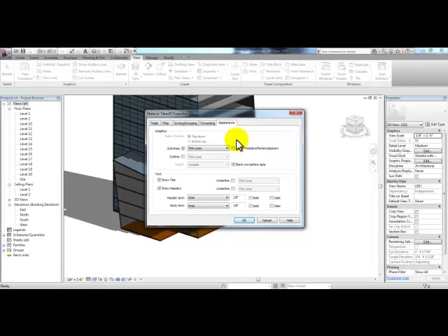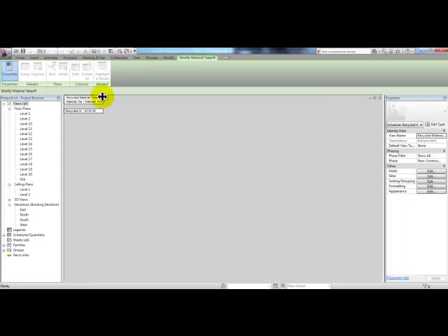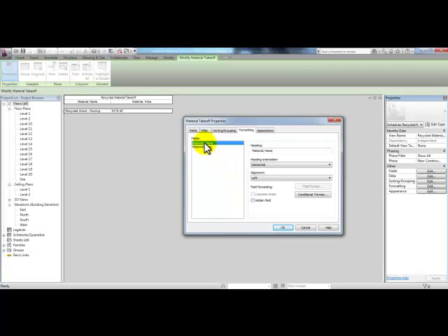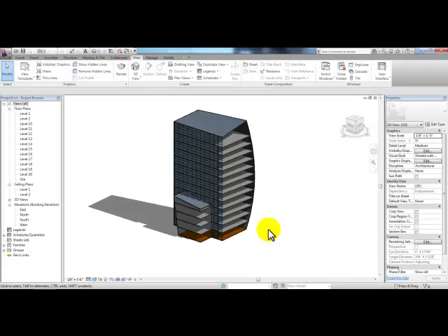In the Appearance tab, you can change other graphics for our schedule. Go ahead and pick OK, and now we have a recycled material takeoff schedule with the name of the flooring and the square footage for our material area. Even after you've created your schedule, in the Properties palette you can pick Formatting and change the material name and area to Center Alignment. Let's go to the 3D view and take a look at Solar Sun Studies.